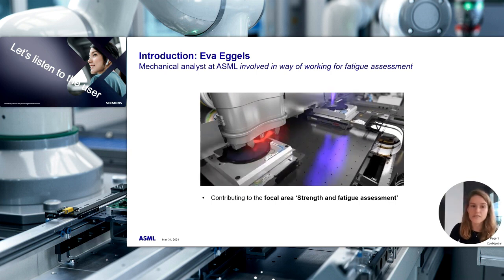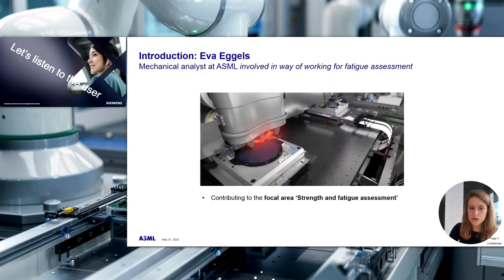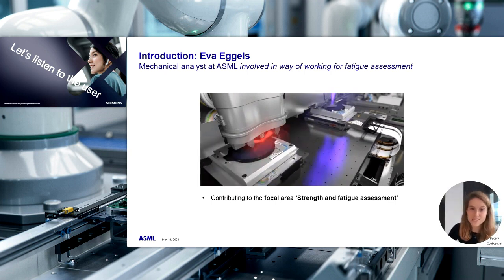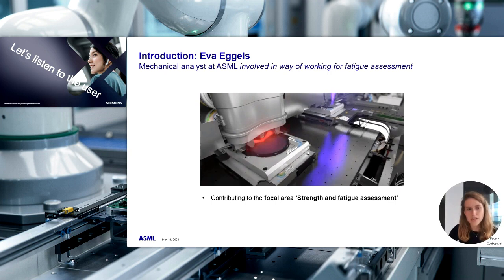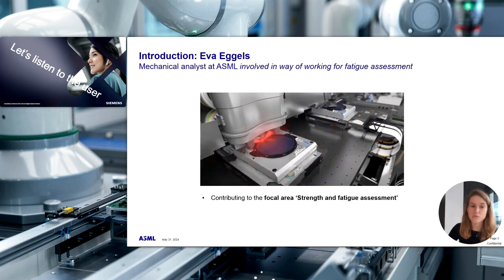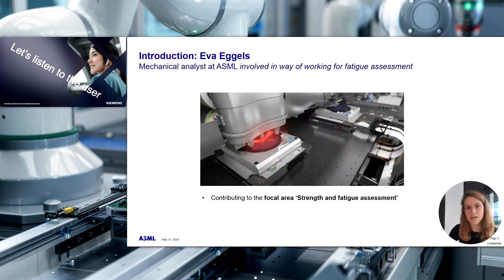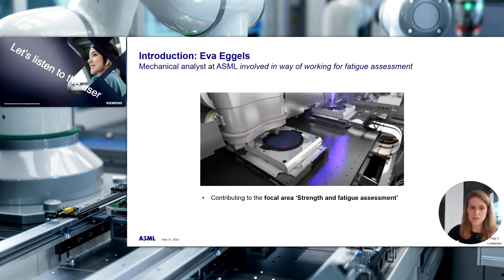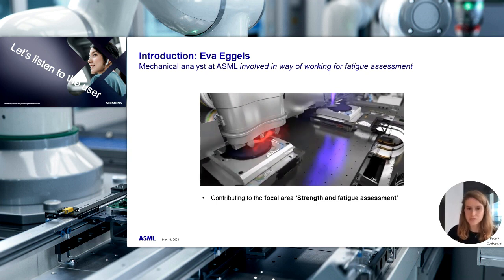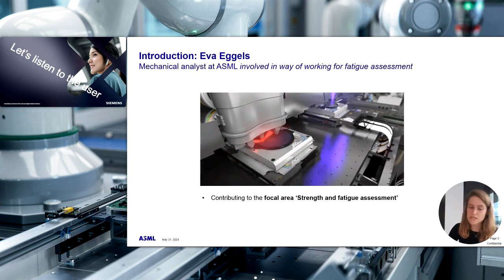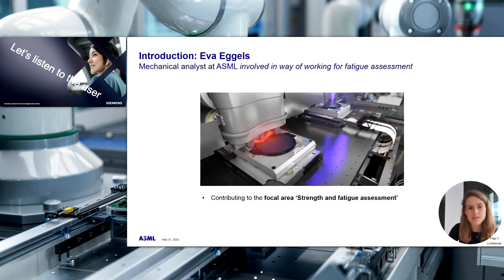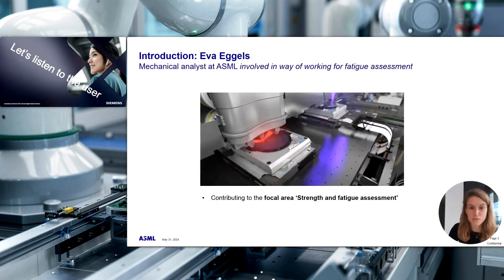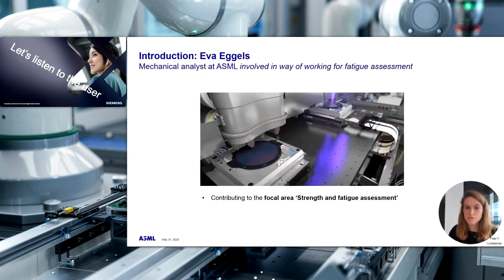In the animation, on the one side the wafer stage is measuring a wafer, and on the other side it's exposing a wafer. And as you can see, it happens at high speed, involving high accelerations. This module should then be able to withstand these high accelerations for a long time, for a large number of cycles. And that's where the topic of fatigue comes into play. This is just one example, but given the complexity of our systems and the high speeds at which it all operates, of course, there are more parts of the system where fatigue becomes really relevant.